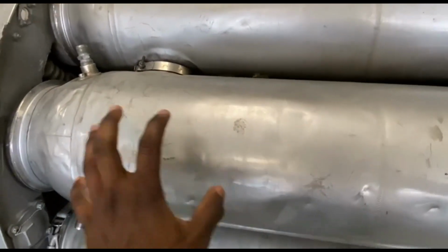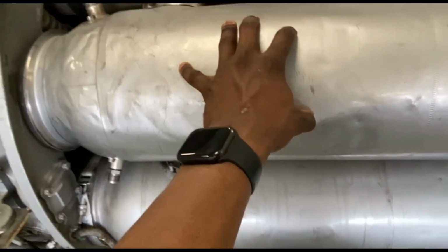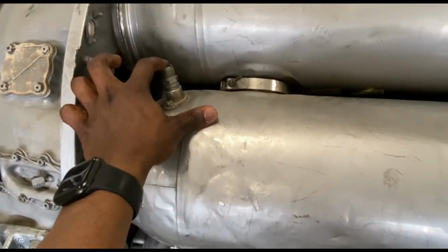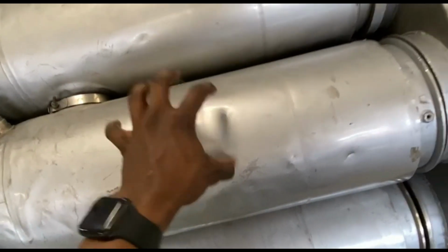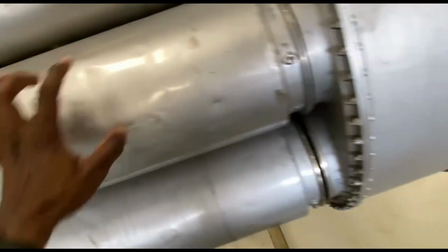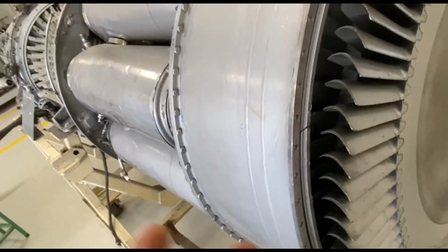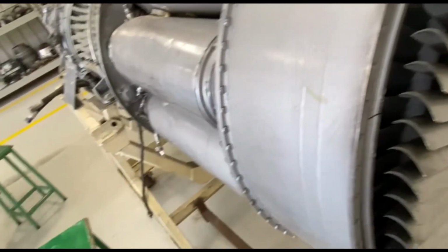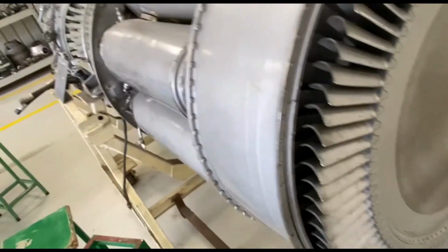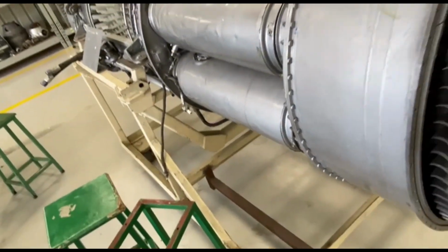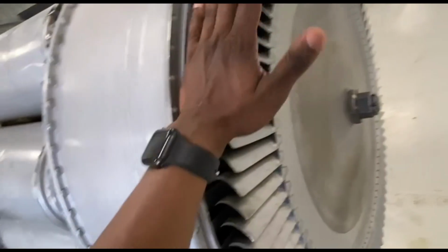Okay, and when it's sending the air to the combustion chamber, it's here in the combustion chamber that we are going to send the fuel, and the ignition will take place here. When the ignition takes place, we are going to send the explosion, the hot air, because we burn the fuel and the air inside. When you compress the air, it also becomes hot. All this power, we burn it and we send it to the turbine section.